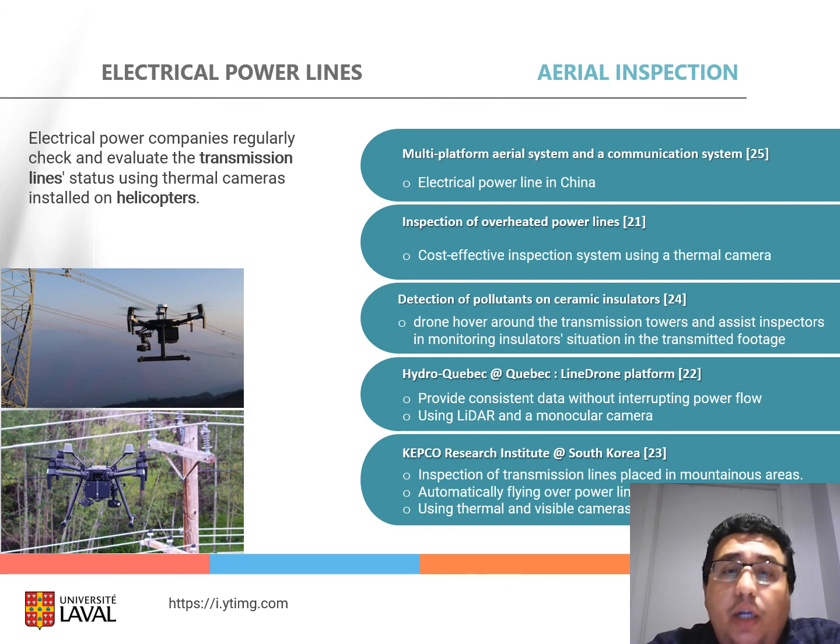For example, in China, they proposed a multi-platform aerial system and a modulated communication system in order to inspect the transmission line in a faster way. Also, Hydro-Quebec, located in Quebec, introduced a line drone platform that used LiDAR and a camera to inspect the transmission lines. KEPCO Research Institution in South Korea inspects the steel towers and the transmission lines using drones, and they use thermal and visible cameras to do so.